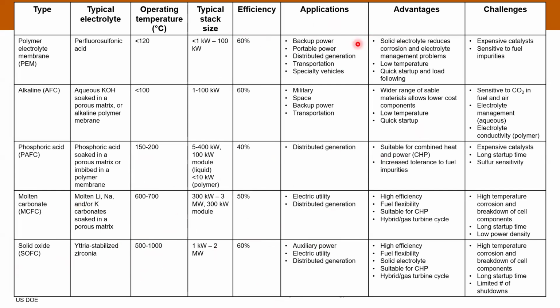There's a lot of work being done on fuel cells right now because there are a lot of challenges associated with this. Some of the catalysts are quite expensive. Some of the electrolytes are complex or hazardous or made out of critical minerals like lithium, yttrium, zirconium. Again, these are things you have to think carefully about. There's no perfect fuel cell at this point, but this is a way of making energy from hydrogen without having to burn it.